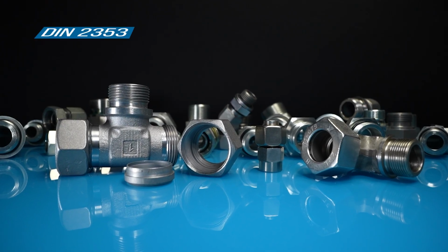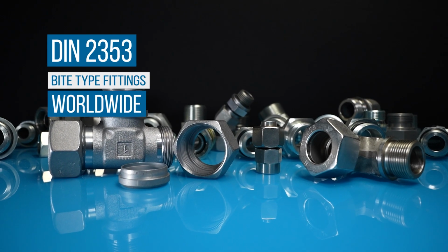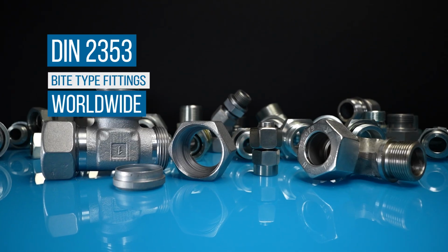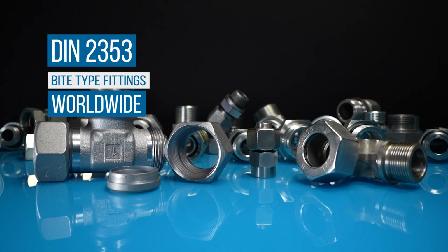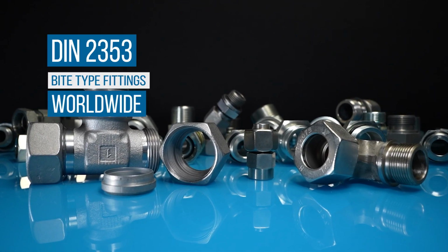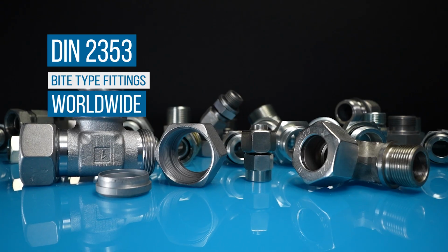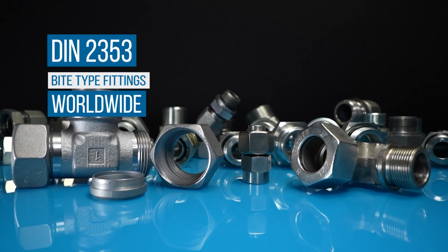There are other varieties of international seals. One example, DIN 2353, are the most widely used bite-type fittings in the world, and they don't require O-rings or other elastomers to make a leak-tight seal. Instead, they seal with metal ferrules.